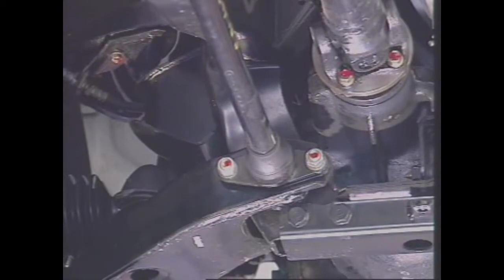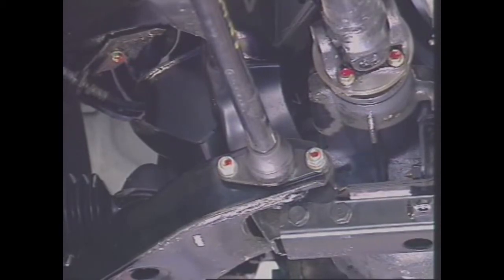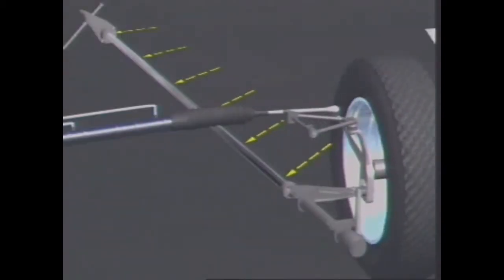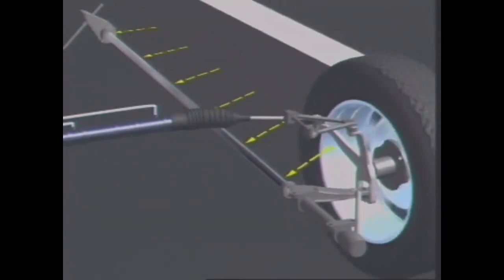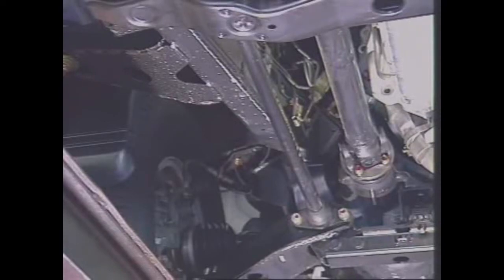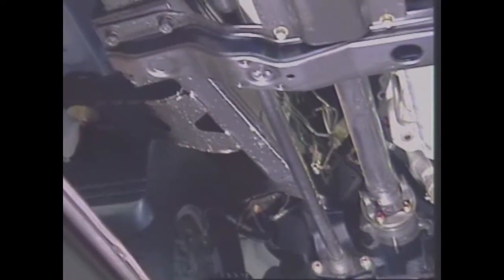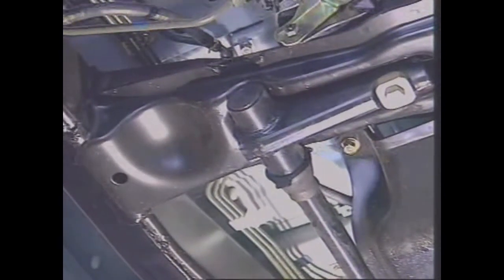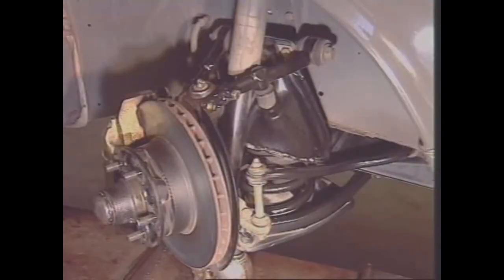The torsion bar is attached at the inner fulcrum point of the wishbone or control arm. As the suspension is deflected, it twists around its center. It can be fitted to the upper or the lower link depending on the type of vehicle. The upper link is shorter than the lower one, irrespective of the springing method used.